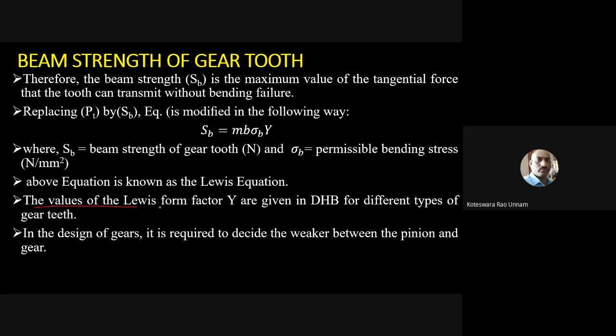The values of Lewis form factor are given in the data book. Design of gear is required to decide the weaker between the pinion and gear. That's what we already discussed.